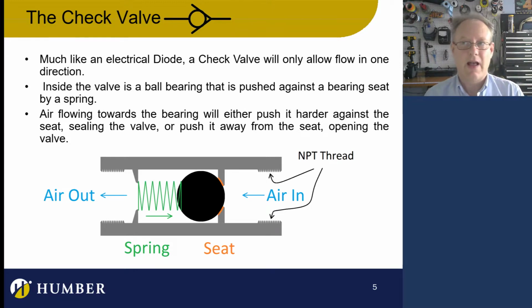And by the way, guys, I know this only through practice, that in your mouth you can generate about 3 psi, maybe 2.5, 3, maybe some people can do a little bit more than 3. But I know that because the cracking pressure, yeah, that's a term, cracking pressure, on a lot of the check valves that I've used over the years is around 3 psi. And I can crack them with my mouth, but just barely. But this thing's really easy to crack.